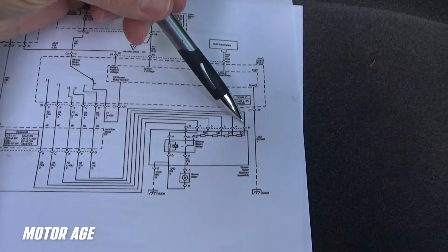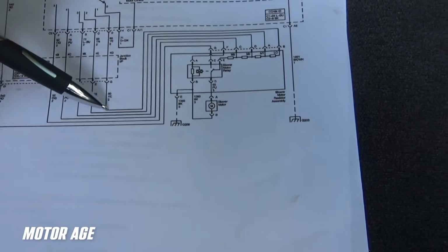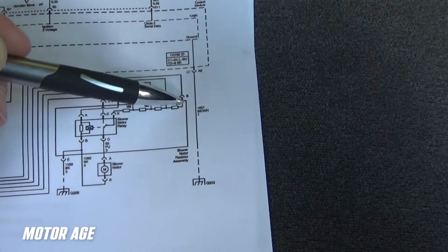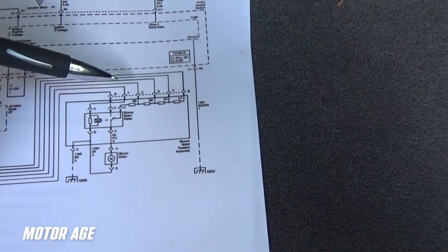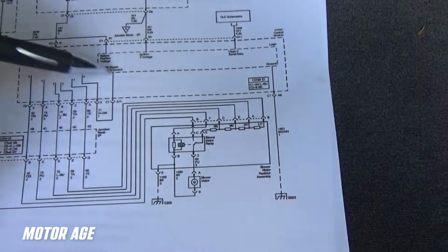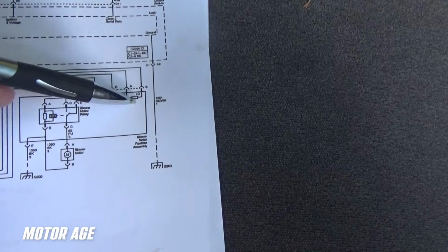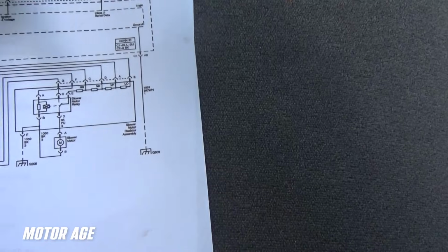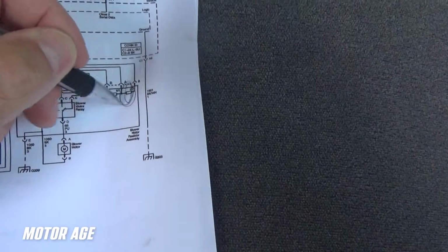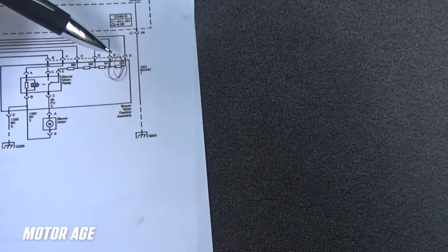12 volts available right here means the switch closed appropriately and allowed voltage to travel down the yellow wire, but it stops here. With voltage present here, and here, and here, and here, and here in their respective switched positions, with the blower motor functional, it infers that this entire resistor module, if you will, is intact. However, the integrity of this resistor module has broken down right here. So this resistor is no good, and by replacing this resistor assembly, we're going to fix the problem.